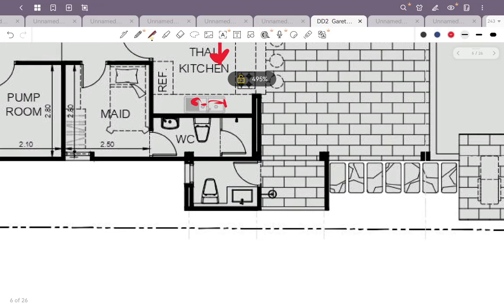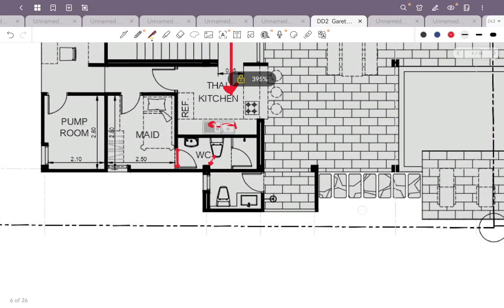Okay, next. If the size of the door here is 80 centimeter, the circulation here should be about 30 cm. For me, I think it's very narrow. And then the toilet bowl is also blocking the way to the shower area.